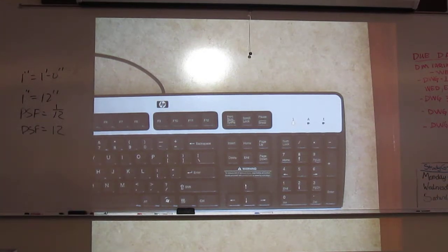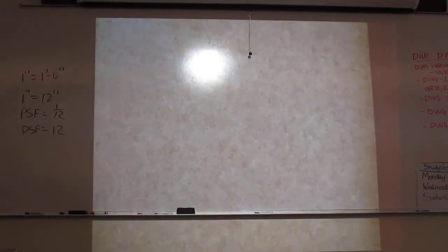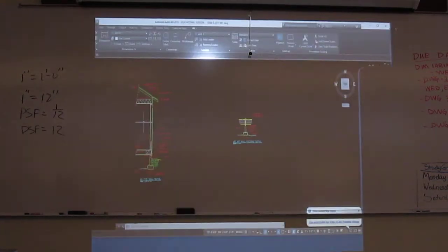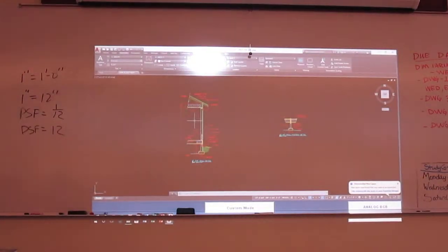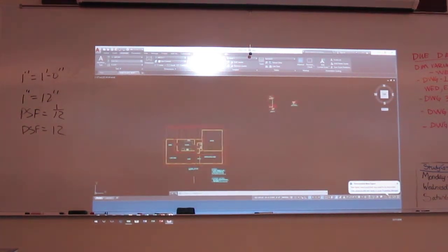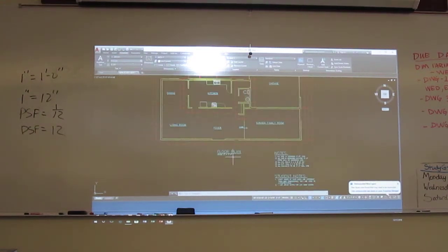Now, once you've got those done, then we're going to set the plot up. That's it. Your drawing's done. Let me just delete this out real quick. In essence, you're going to have 2 XREFs. You got these 2 XREFs done in different ways, but they're completed. You've got your floor plan. Again, here's those titles we're talking about where you'll have stuff.